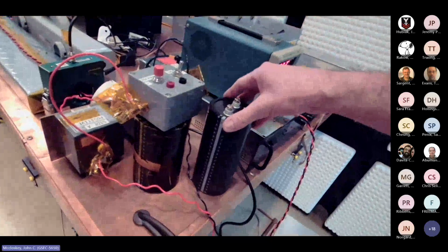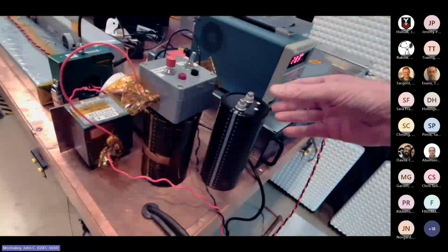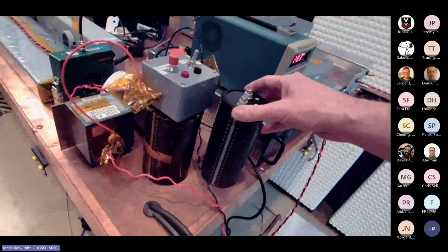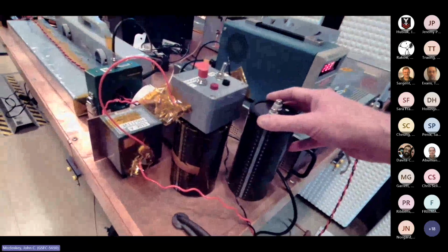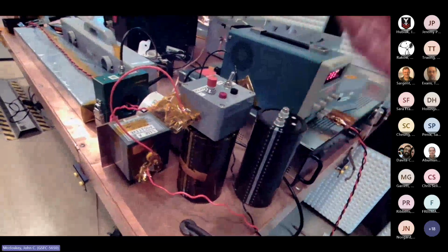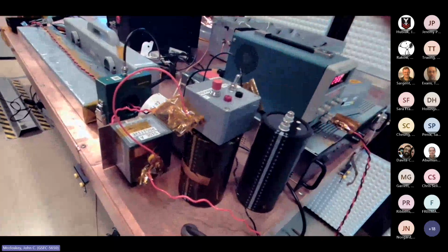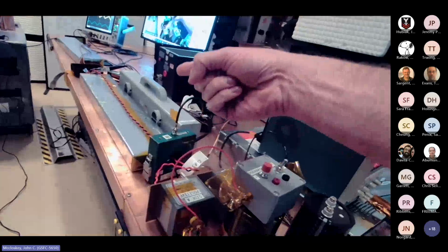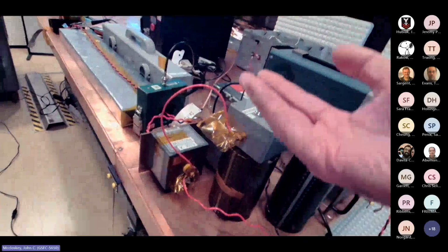And the 10,000 microfarad is about an ohm at about 20 hertz, give or take. So the whole purpose is to look like a battery down to very low frequencies, so that from a conducted emission standpoint, which we're going to get to here, whatever noise currents your EUT wants to draw, your power source can feed it. Right?